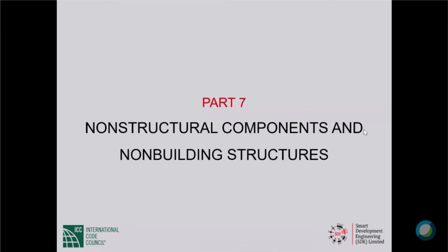Okay. Now the diaphragm flexibility, or whether it is a stiff diaphragm or a flexible diaphragm, does not depend on whether it's a steel building or a concrete building. Diaphragm flexibility is defined very, very specifically in ASCE 7. I believe the section number is 12.3. I can check very quickly. I am pretty sure it's 12. Let me see. Yeah. So 12.3 is the section where you will find answers to flexible versus rigid diaphragm.